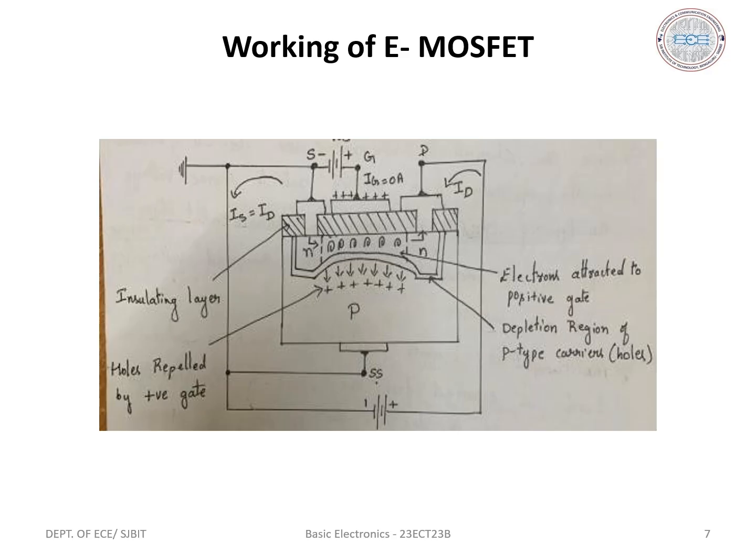Okay, so the value of VGS at which the inversion layer is created is called the threshold voltage. For how much value of gate to source voltage the inversion layer gets created, that particular voltage is called VT. VT is nothing but the threshold voltage. Okay, so this is how the E MOSFET is going to work.